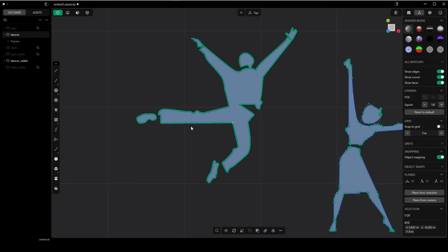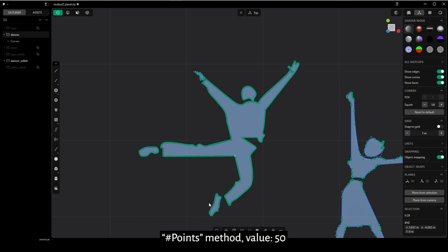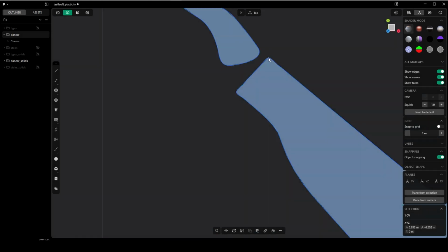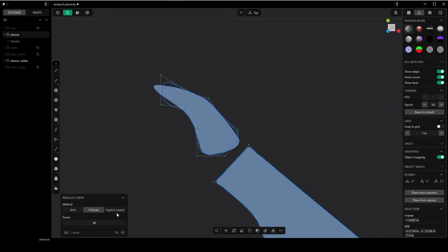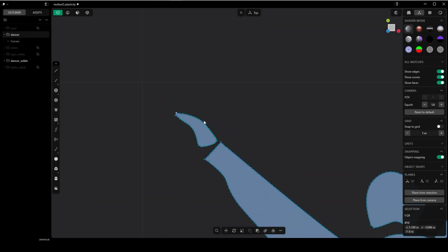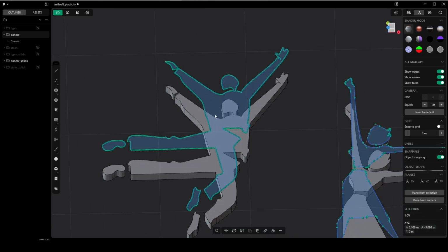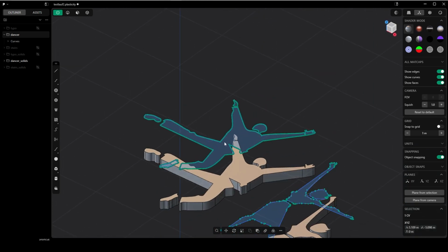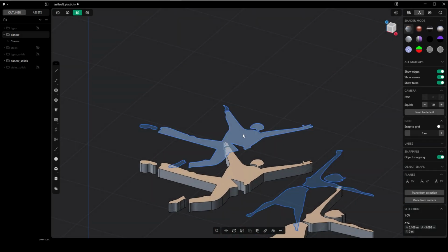By the way, I did these two curves off the record with F, rebuild, and I gave them a value of 50. And let's rebuild this one also. Let's try something like 30 or even 40. 40 looks okay. And you can fine tune if that makes you happy. But I don't want to waste your time playing around with these small details nobody will notice.